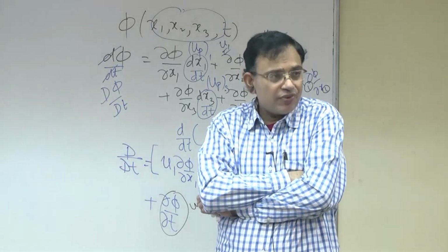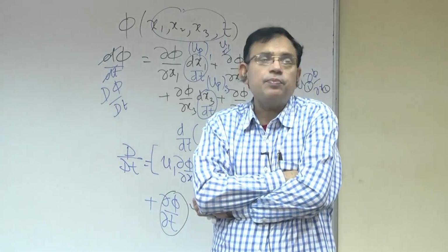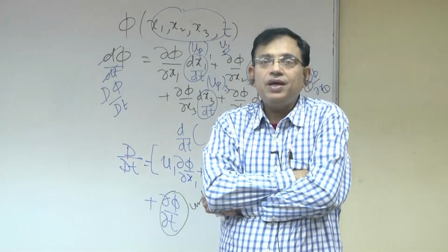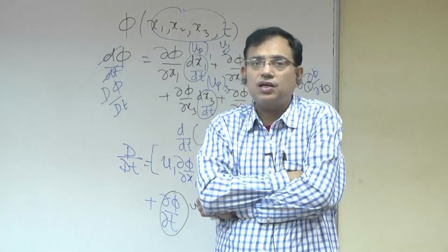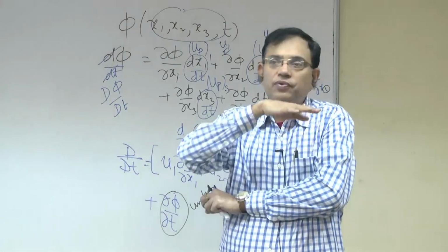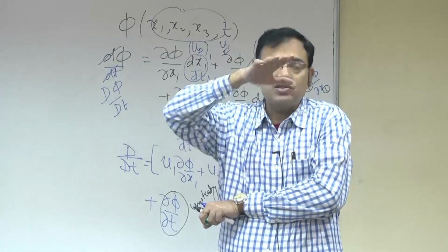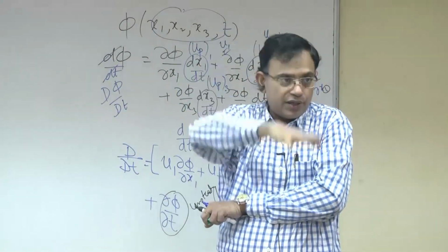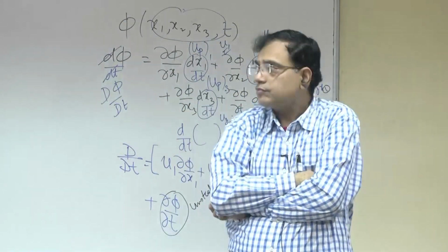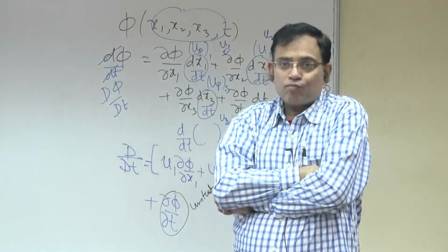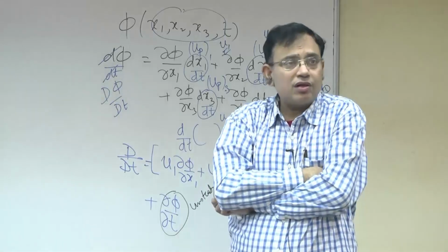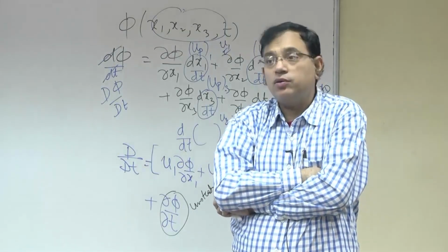Density could also be a function of temperature, but you have many problems where the fluid behaves like incompressible, but density changes with temperature just because of effects like thermal stratification. That means you have light fluid at the top and heavy fluid at the bottom. So here we are talking not about incompressible fluid, but incompressible flow.